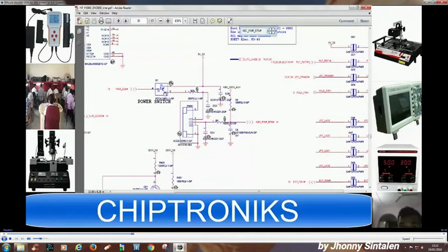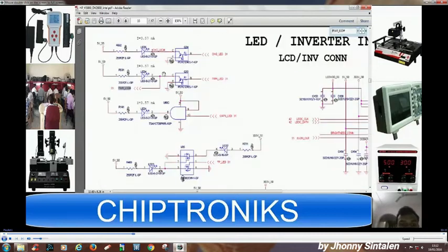What kind of transistor is this? Can you tell me? The arrow is inside, so it is PNP, and a PNP becomes active only when the current flows from emitter to collector with the base grounded, and here the base is connected with the PWR_LED signal. Now this PWR_LED signal is coming from another transistor, and this transistor's base is connected with